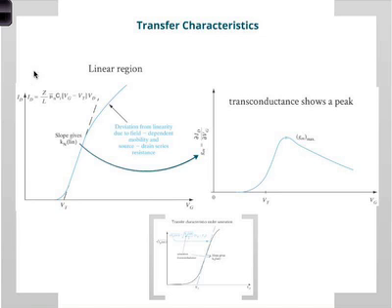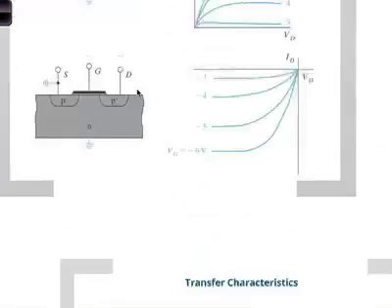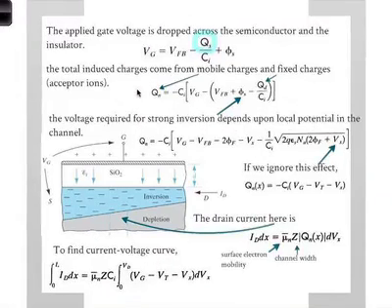So this equation is exactly the same as what we had before. This should be a straight line, but at very high gate voltages, you get a deviation from linearity because you get very high electric fields in the transverse direction, perpendicular to the flow of electrons. Okay, so let's think about that also for a second before I keep going. Let's look at this picture for a second.